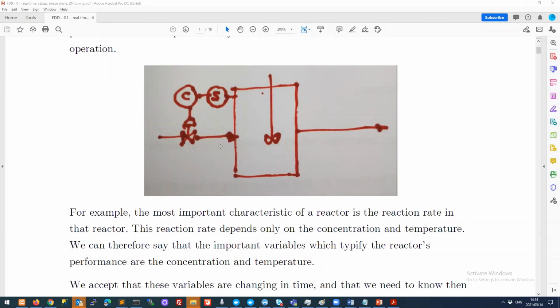In chemical engineering, it's all about the streams, right? That's one thing we can easily control. We can stick a flow controller on a stream, and we can raise or lower the flow rate. That depends on whether you've got enough pressure behind the stream to raise it, of course. But that's what it comes down to in chemical engineering.